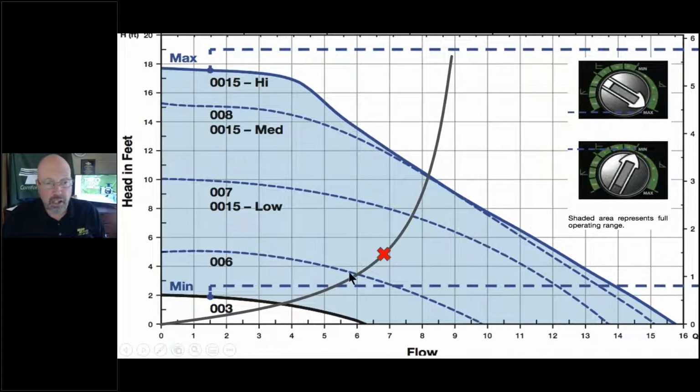So like I said, we get in between, just over the first dot, and now you've got the perfect size circulator for your application. And as our zones get smaller, we can really dial it into where we need it to be. So I would say right here, we're going to have an 8-watt, 9-watt circulator operating our house. Out here, we're going to be running around 20 watts at that 7 gallons a minute, 5 foot of head, 70,000 BTUs heating the house.